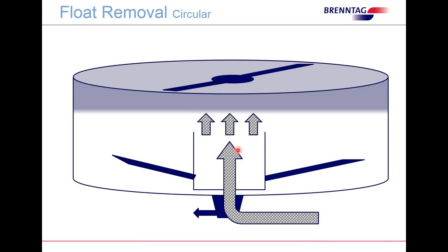And because of this hood right here, this water was coming out and shooting very quickly through the DAF unit, not giving ample time for it to rise. We took this off, and immediately the suspended material, the pin floc coming out of the DAF, was alleviated, and everything worked well. Nobody had any idea how or why somebody would have placed a hood on this, but it was done, and nobody knew it was there. So by simply opening this up and removing the restriction, the carryover from the DAF was alleviated.